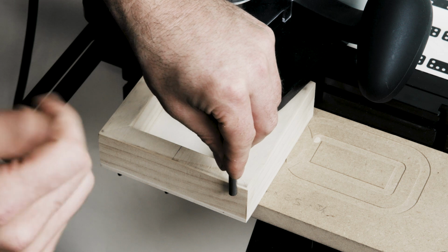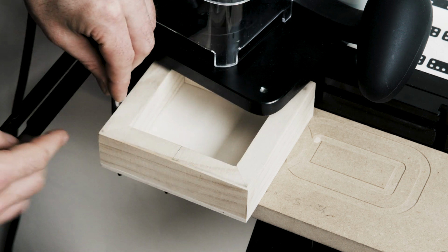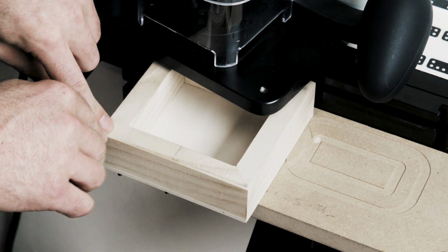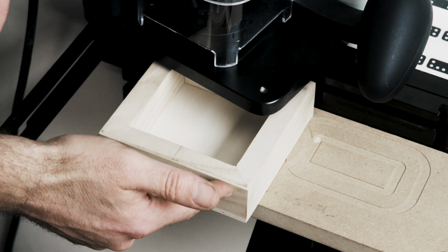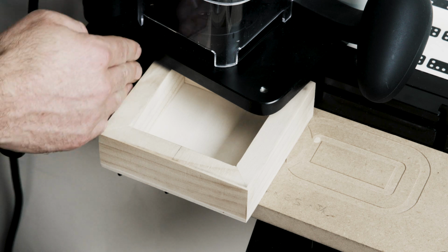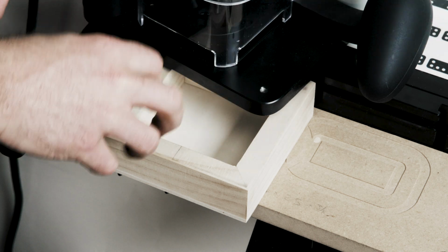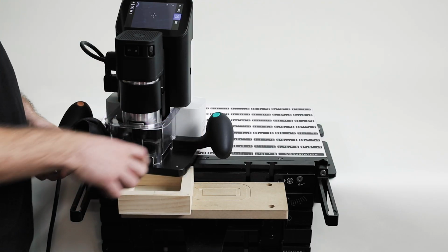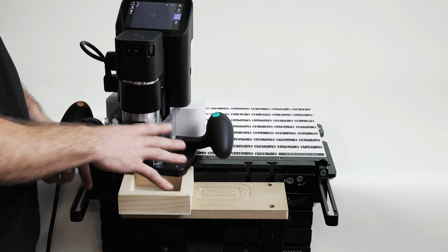Just lightly touch and click probe, then move over, lightly touch again, and we come around a corner to get our y-axis and probe there. From that point on, we have a clear reference at 0 in x along this face and 0 in y along this face. We can then place elements relative to that position, an inch in from either axis or in the center here, however you want to do it, and know that it's always going to be aligned. Its orientation and its position will be explicitly tied to this edge.